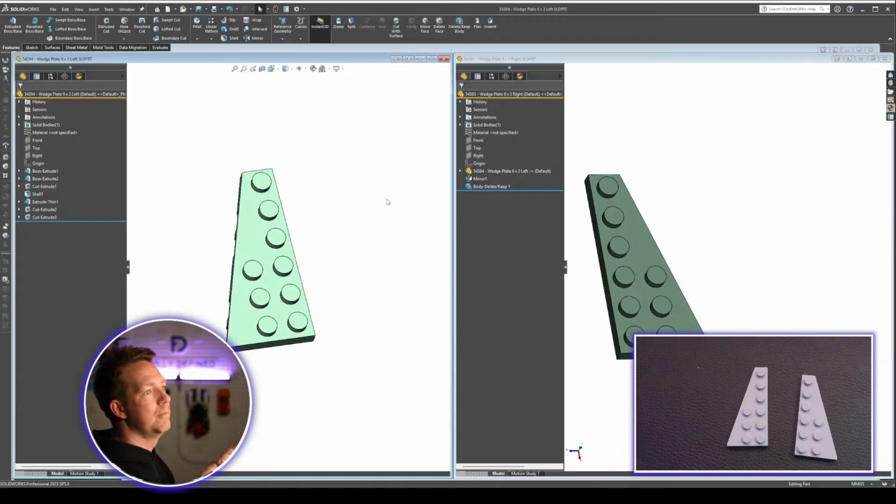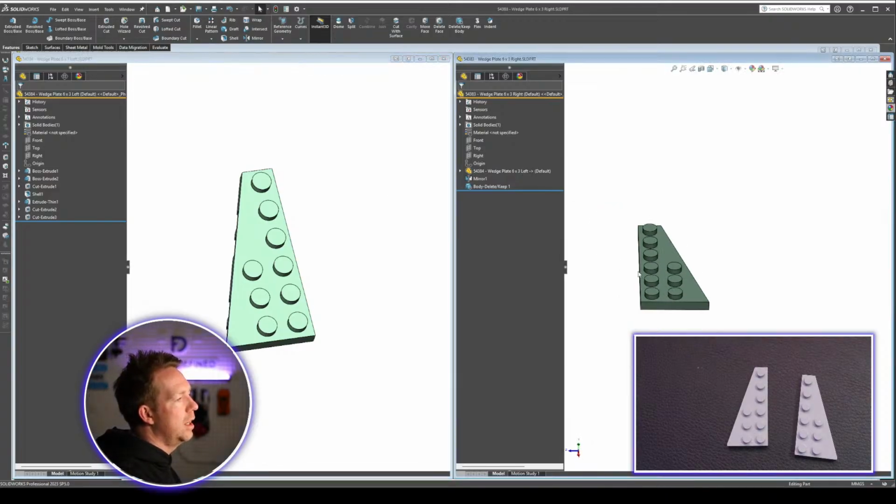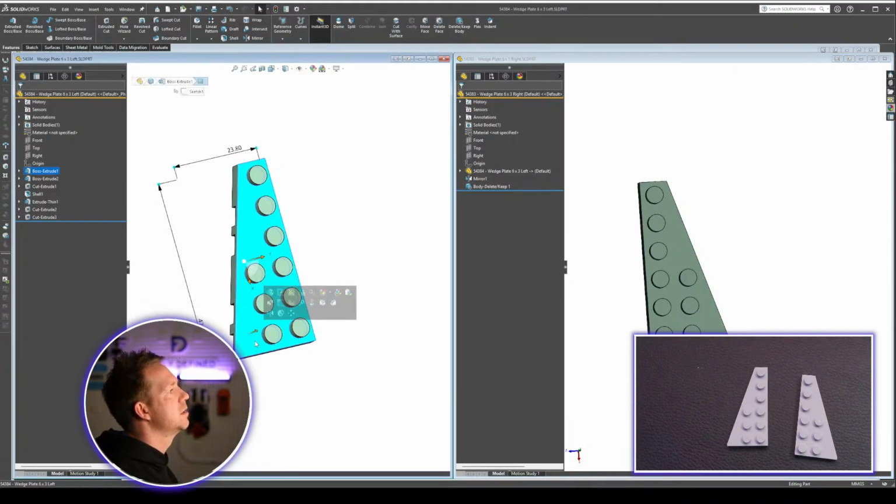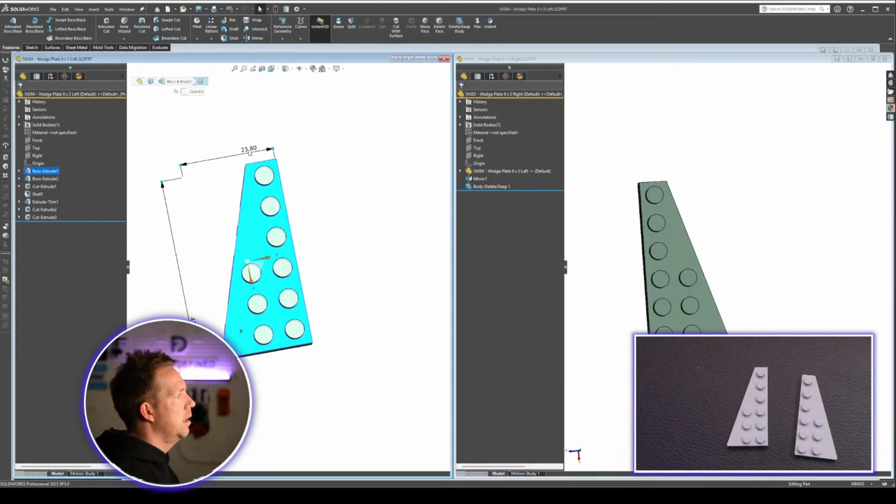But the parts would have the same name, all right, which wouldn't make sense. I'd have a part left and another part left, but the left version is a mirror of the original. Doesn't quite work. There is a mirror. The mirror components feature within assemblies can allow you to create a mirrored version like I've just done here. I've just shown you a cleaner way of doing it. So I see this option as the one that, okay, let's assume later I'm going to make some changes to this to get, let's say, interference out of the way or clean up any problems that I find. I'm just going to do a really obvious one right now. Let's say that I need to change this to 26.